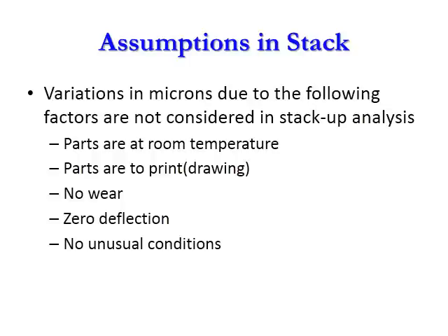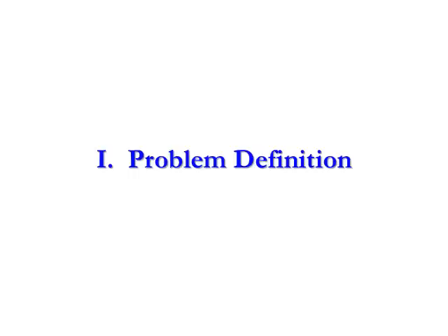Assumptions in stackup. Variations in microns due to the following factors are not considered in stackup analysis. Parts are at room temperature, parts are to print drawing, no wear, zero deflection, no unusual conditions.